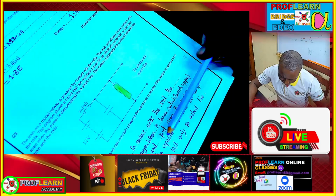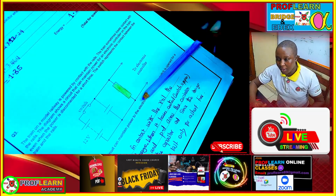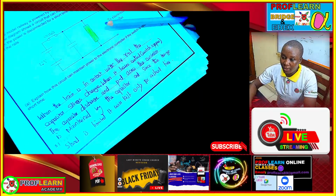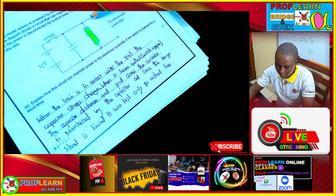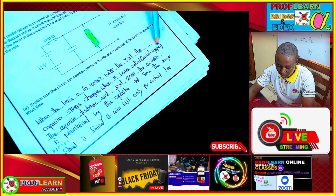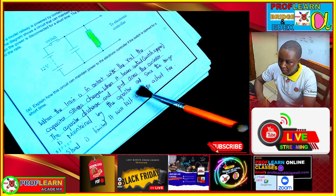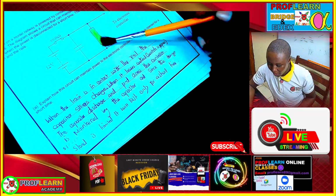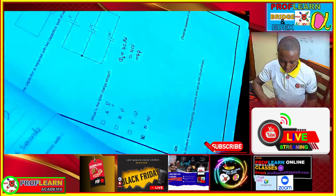Then we are supposed to explain how the circuit maintains the power to the electronics. So we understand when the train is in contact with the rail, the battery is going to supply power to the electronic controller. When it loses contact, the switch opens, and then you're going to realize that the capacitor is going to discharge at that given point. When the capacitor is discharging, it is going to be supplying power to this electronic controller. That's basically how this circuit is going to work.